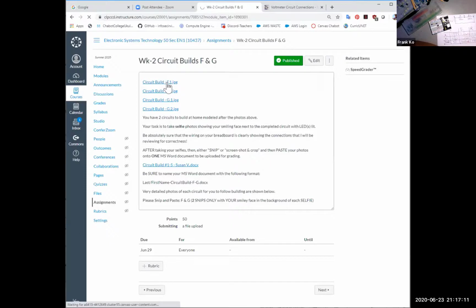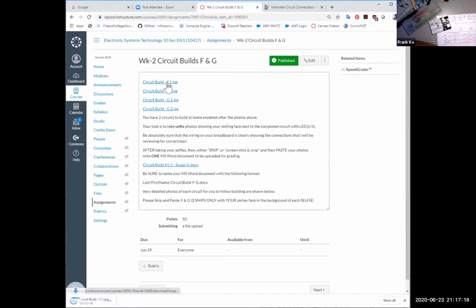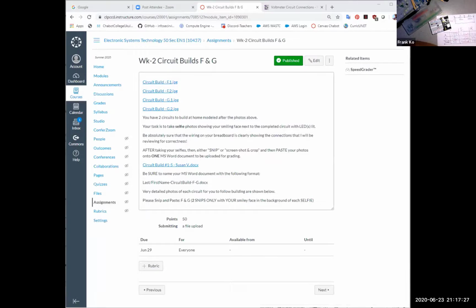However, the circuit builds are pretty easy, but the labeling is very specific. So here you go. This is the same 2 resistor circuit that we built. However, I've labeled these points of interest. So instead of the 100 and 330, I put in a 220 and a 330. So when you go to build this, your R1 is 220, your R2 can stay as the 330.